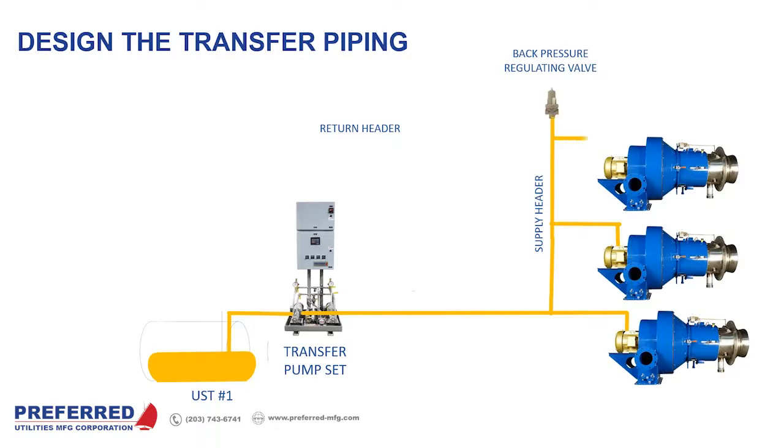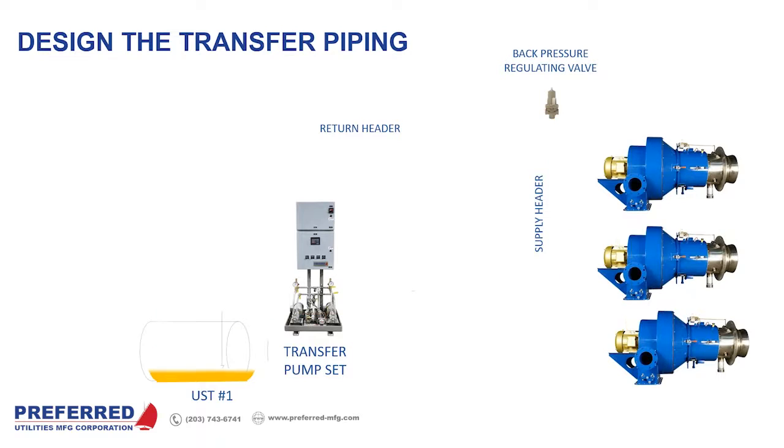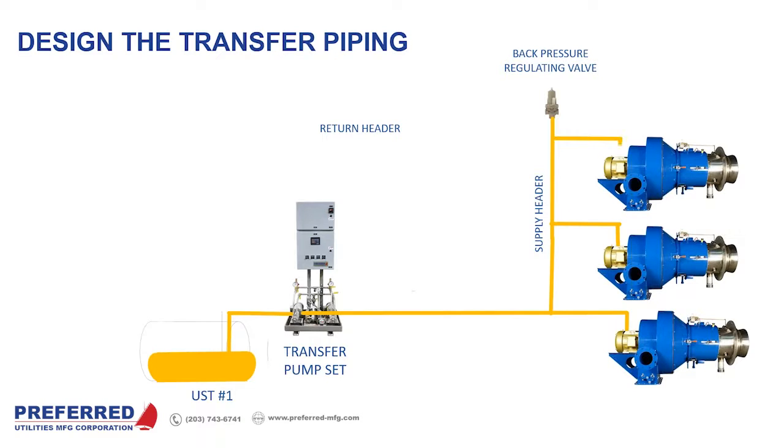And there's really two types of burners. The oil line can deadhead like this one. And if we went back a couple of slides to that VA hospital schematic I showed you, the oil line's there deadheaded at the burner. Some burners are going to have a 3-way valve as their first safety shutoff valve, so that when the burner is not running, they're returning oil back to the return header. So again, you need to take a look at the type of burner that's being supplied and see if it has a return line or not.